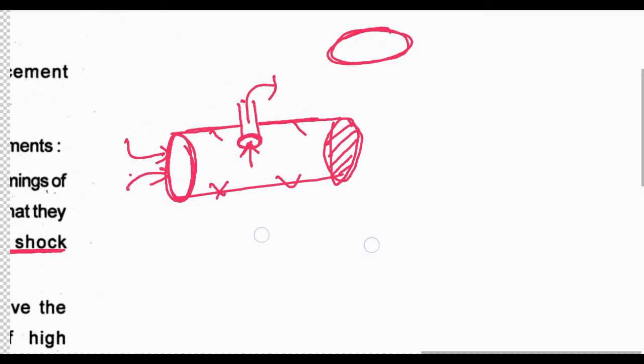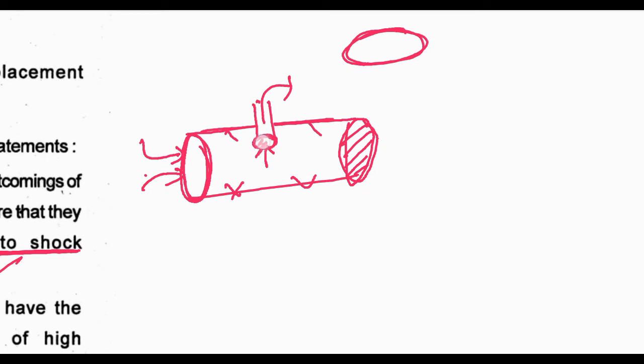So what is this saying? Suppose this diaphragm consists of a polymer piezoelectric material, like polyvinylidene fluoride or polyvinylidene trifluoroethylene. If it is made of this, and we are allowing hydrofluoric acid or sulfuric acid, H2SO4, then as this is a polymeric diaphragm, it will be melted, because not all polymers are resistive to acids.